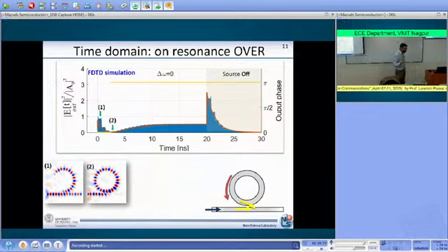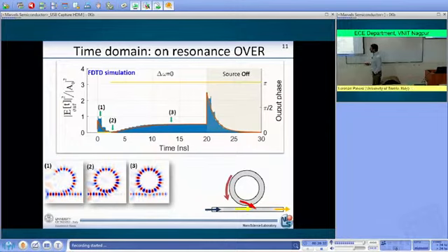But then you are still providing optical signal at the input. And therefore this condition of destructive interference is now occurring between a field that is large and a field that is small. The field inside the microring resonator dominates with respect to the field that is coming in, and so you lose the condition of perfect destructive interference. Therefore, some of the field coming out from the microring resonator is transmitted by the bus waveguide, and the intensity is increasing.